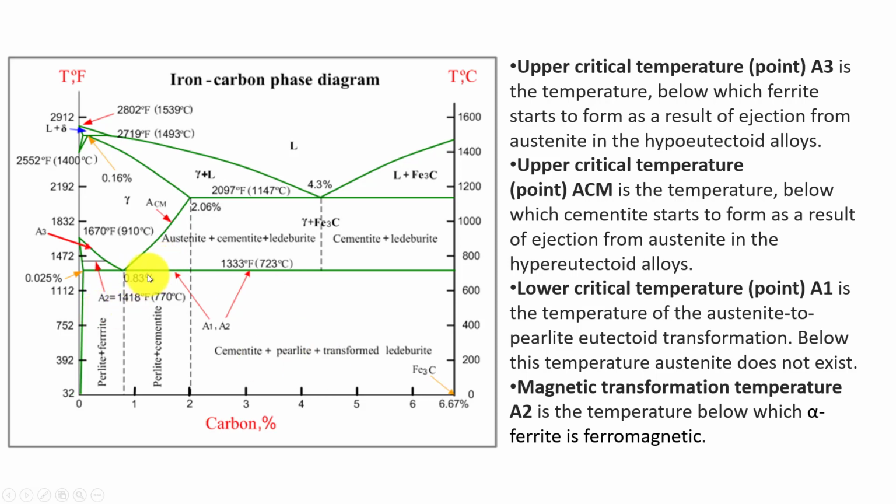So if I'm going to do something like a coating or a plating and they're going to use heat, and let's say they go up to 600 degrees Fahrenheit, then what they're saying is it's a lower critical process, is how we would use that in terminology. We didn't go above that, so we're not seeing any austenite coming out of solution or any real effects on the material. So a lot of times we talk about lower critical. So upper critical, lower critical.